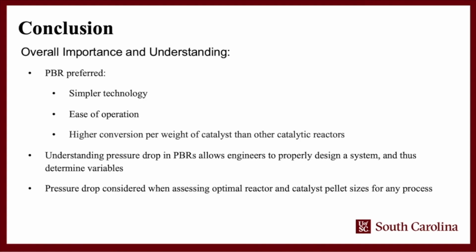On the understanding of it, understanding how to calculate pressure drop in packed bed reactors allows engineers to properly design a system and thus determine variables such as, again, size, diameter, among other things. Pressure drop should be taken into consideration when assessing optimal reactor and catalyst pellet sizes for any process, just because it is super important and it affects a system in general.